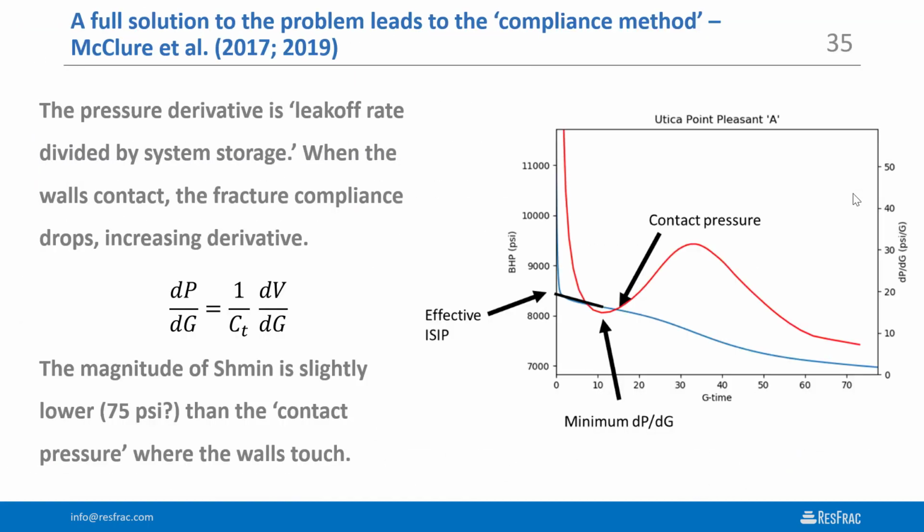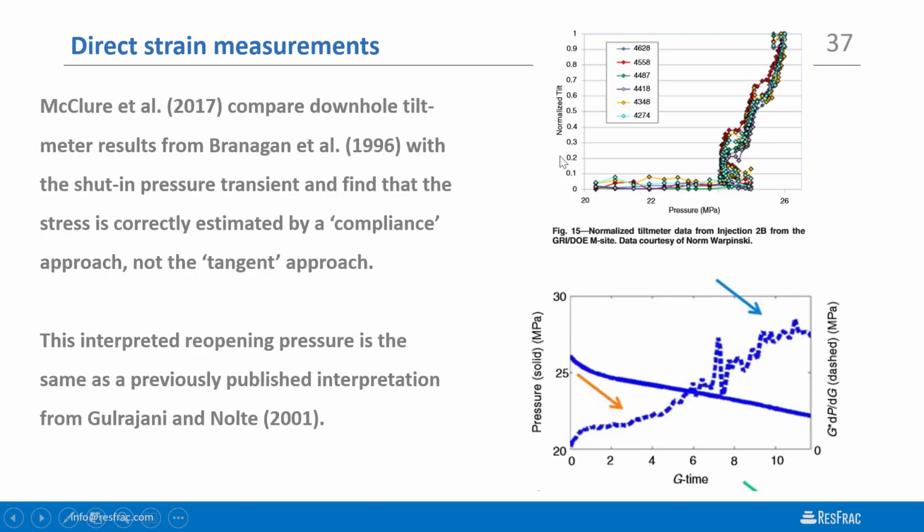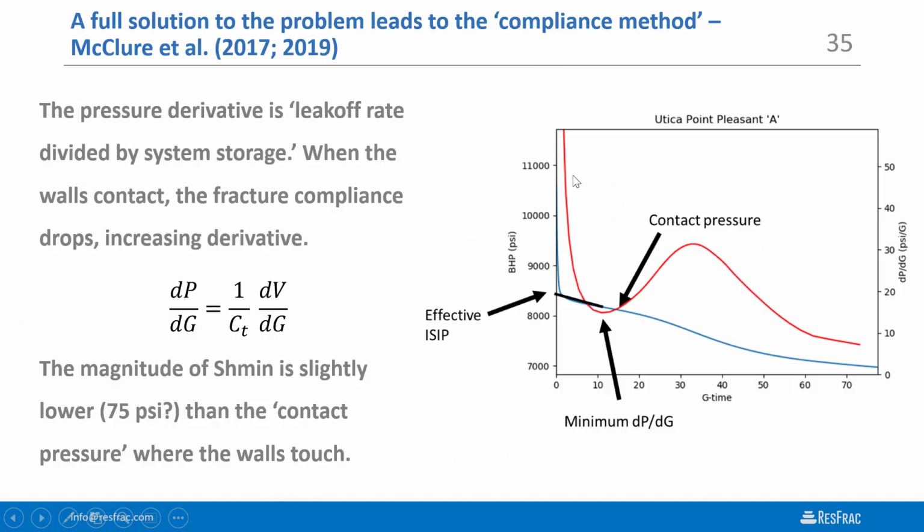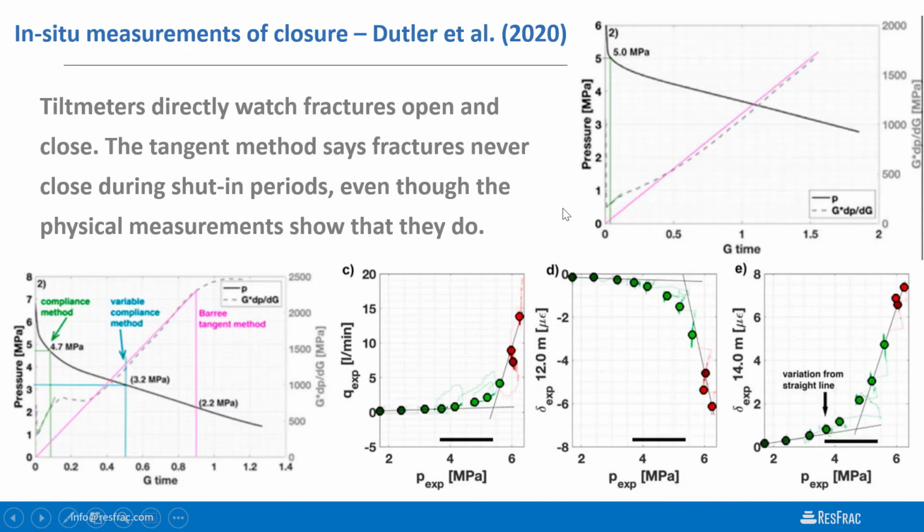So actually, I'll just go back here, and we can see here in this URTeC shale example, the actual pressure at shut-in was like 11,500, maybe 12,000 psi. Very quickly dropped off down here to closer to 8,300 or so. We think this is near wellbore tortuosity. I'll talk about that later, and that's related to the fact that this is a horizontal well.